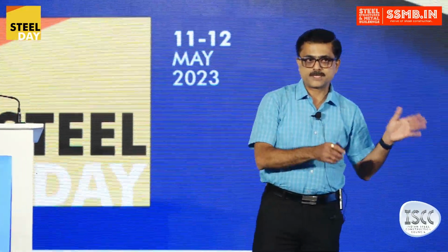However, with the inception of PEB, high yield strength material started being used, and very sophisticated welding techniques were introduced. So the hot roll sections are being replaced with plate sections, which are converted by welding plates into I sections or the required form of sections. That's how PEB came into the picture, and after 15 years, in this era, it is the most popular structural type used in India, and worldwide as well.